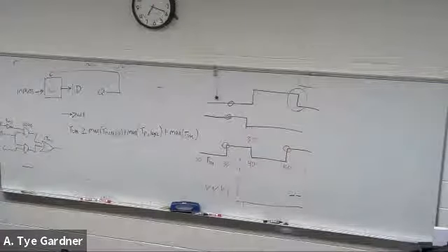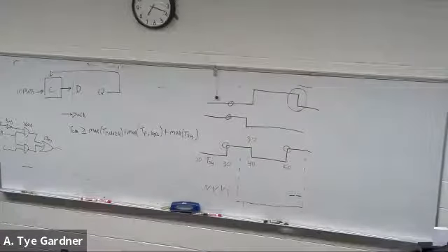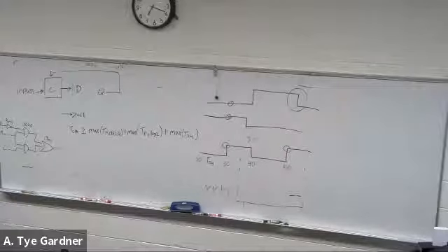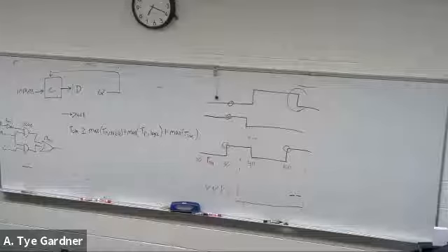So what you'll notice here, if you're very careful, is it doesn't care about the hold time. And that's simply, it just isn't something that's going to come up from you changing the clock. Speeding up the clock isn't going to be an issue for the hold time nearly as fast as it is going to be a problem for the setup time.